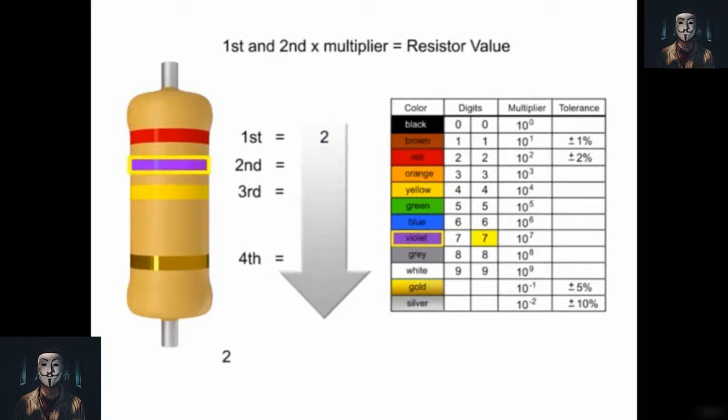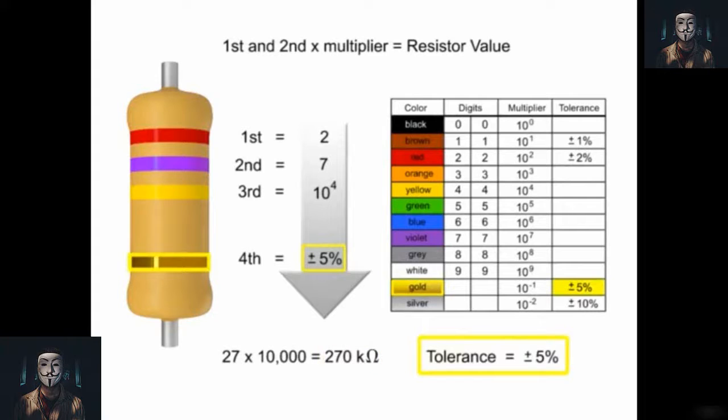Variable resistors. Variable resistors provide for an infinite number of resistance values within a range. The most common types of variable resistors are rheostats and potentiometers. The rheostat is a 2-terminal variable resistor used to regulate the strength of an electrical current.